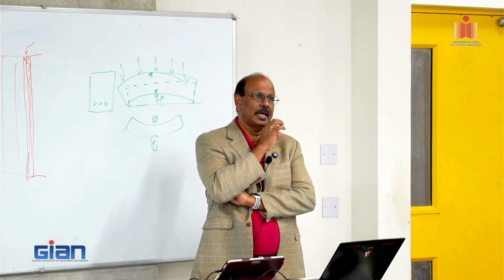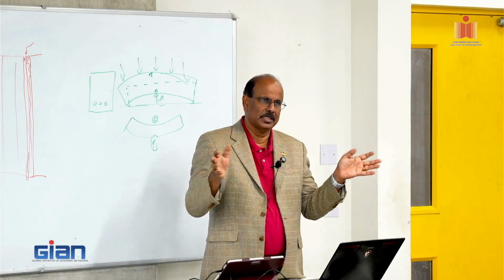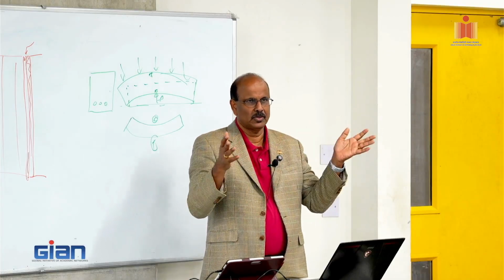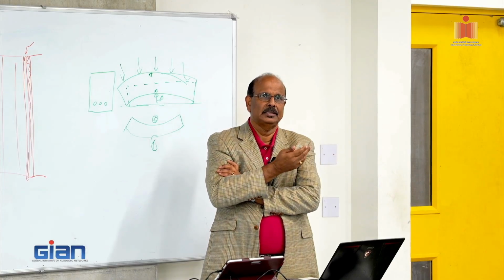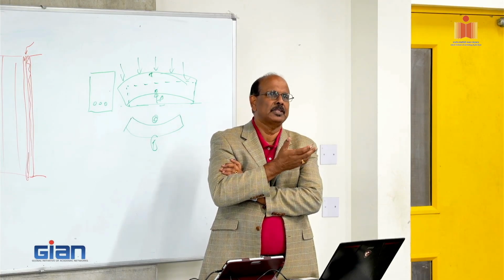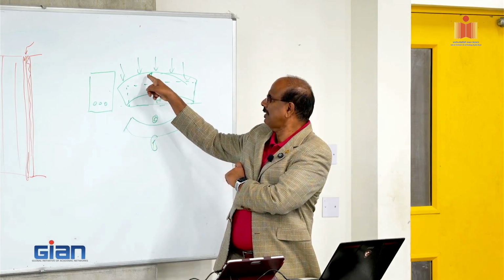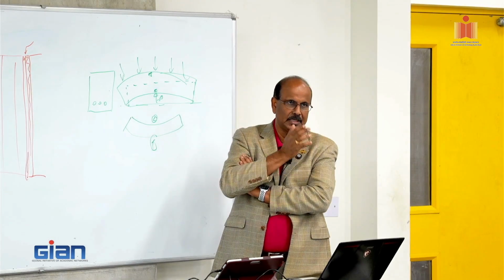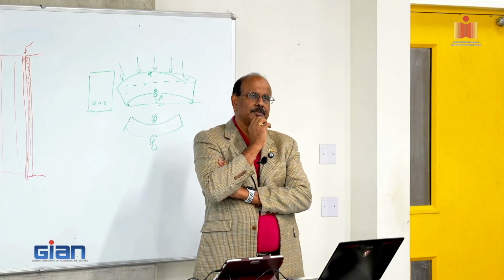Again, that gets determined by the span length, the amount of pre-stressing, the cost associated with it, and all that stuff, right? But ideally, keeping it flat keeps everything in compression. If I go the other way, I potentially have tension develop at the top, provided that tension is within limits. Yes, it can be beneficial.